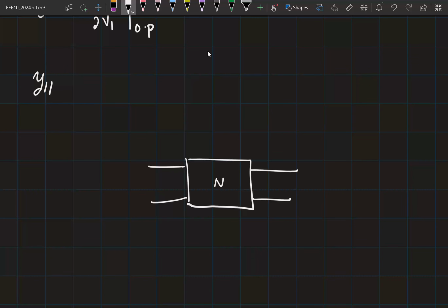So I have given you a network with two ports. I've given you all the voltage sources, current sources, any measuring instrument you need. So you'll short the output. So on what basis are you telling me this? Based on this expression, I1 equal to Y11 into V1 plus Y12 into V2, right? So it looks like if I make V2 equal to 0 and then I take I1 by V1, I should get Y11, right? So is this all I have to do or am I missing something?